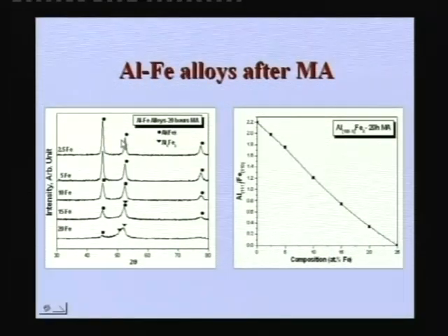200. And we always know that the second peak has a lower intensity than the first peak in most of the pure metals. So, as a result, you can see here, if you do pure aluminum also, you get a similar situation, that aluminum 111 will be more intense, aluminum 200, aluminum 220 will be still lower intense. But what you see here is, as I keep on increasing iron amount, this peak is decreasing, whereas this peak